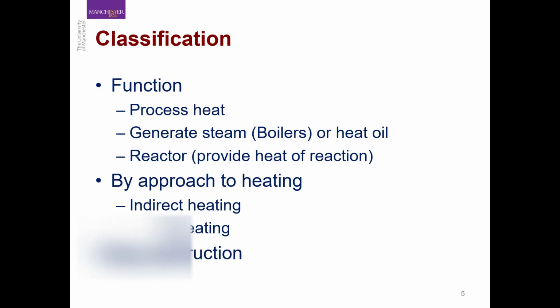Okay, so fired heaters can be classified based on different factors. For example, what is their function, what is the heating method, and by construction as well. So if we talk about function, fired heaters are designed to produce heat to provide it to the process, and that can be direct application of heat to satisfy the heating requirement of the process, or fired heaters can be used to generate secondary types of hot utilities.